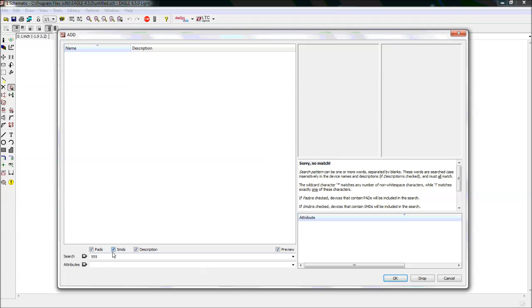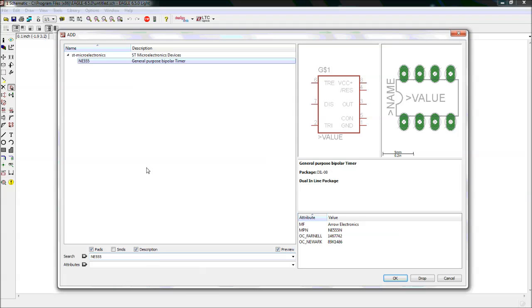Why is it? Because it's just not a 555. It is an LM555, or NE555. That means companies gave their initial name to them, just like Fairchild had given LM555, National Semiconductor has given NE555. So let's search for LM555. Fine. Still we got no such match. That means this is not included in any library. Now we are searching for an NE555. Let's search. We got it.